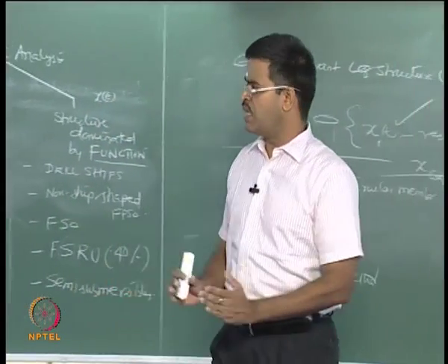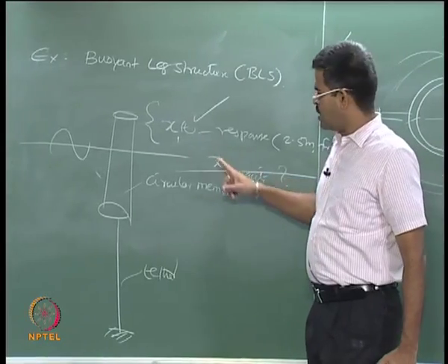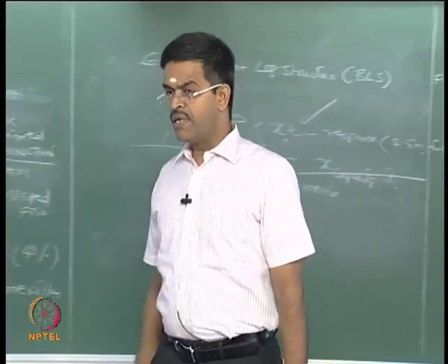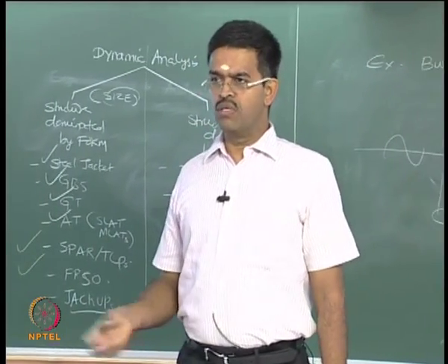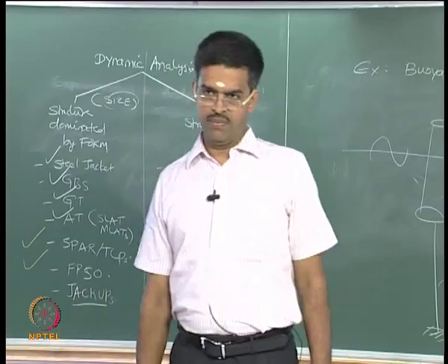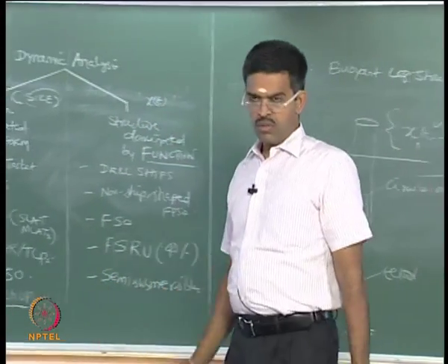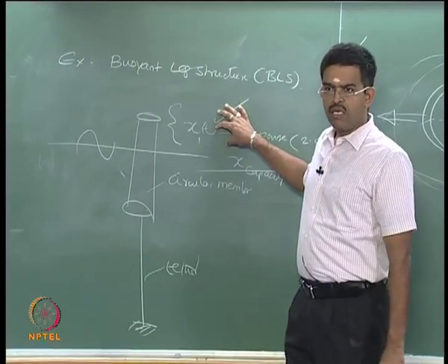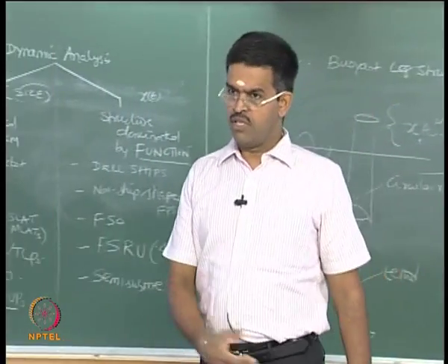Remember this, we are not combining these two. We are looking only at the response feature of this, we are not looking at the capacity of this. So it is very clear, deformation capacity is not looked at. Therefore, material characteristics will not play a major role in dynamic analysis at a primitive level. Then one can ask, how can you include the material characteristics in the dynamic analysis? I can say you do non-linear dynamic analysis, where non-linearity can come from many sources.